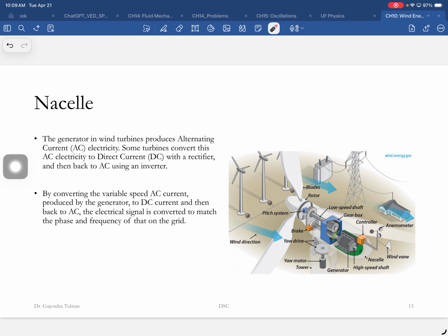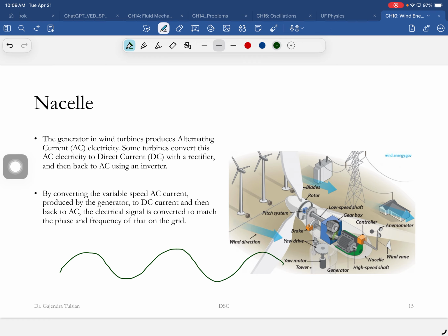Now, when this guy feeds his electricity to the grid and this guy feeds his electricity to the grid, if the voltage in the grid is like this, when you feed electricity to the grid, you've got to match that waveform. The one in Palm Coast has to do that. The one in Jacksonville has to do exactly the same thing.